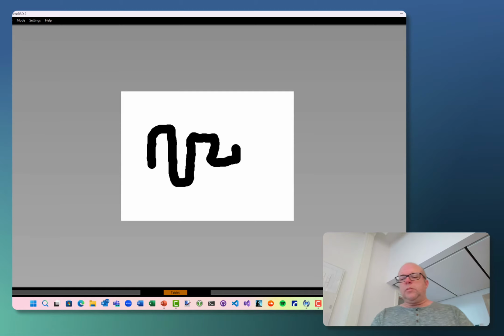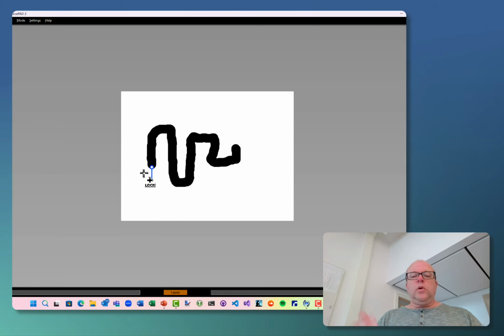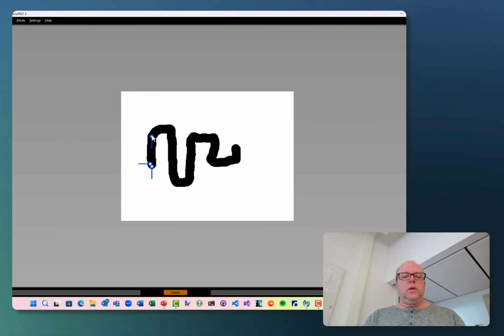So, the next step, if I go to the physics mode, here you have two choices. You can apply loads and you can apply boundary conditions. So this one here is a boundary condition, and this symbol means that it's like a roller. So the structure can move in this direction, but not up and down. And if we want to lock it in both X and Y direction, we can put another constraint in here. And you can see I can change the direction here. And we can put one here on top as well.